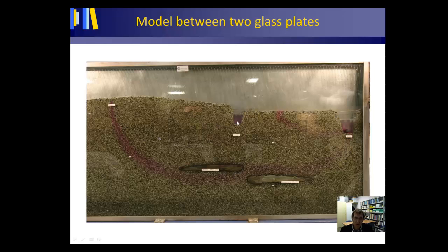Water is moving out of the model in this ditch, and water is moving out of the model in this river. The water table is approximately like this. Of course, it coincides with the surface water level here, and also here we have the water table like this, and it coincides with your surface water level here.